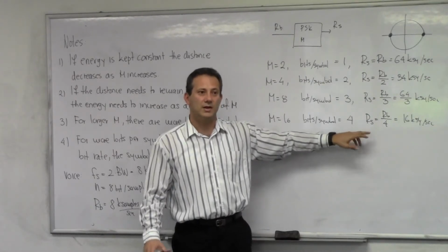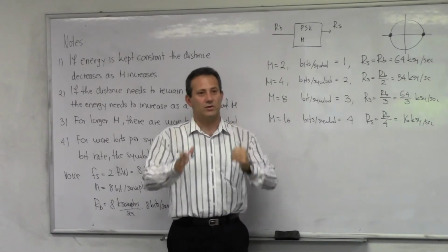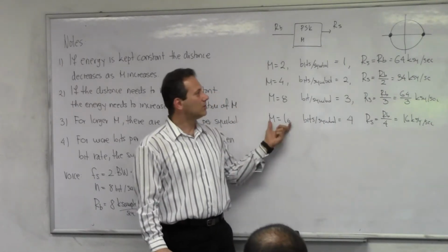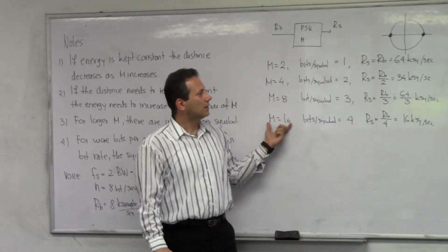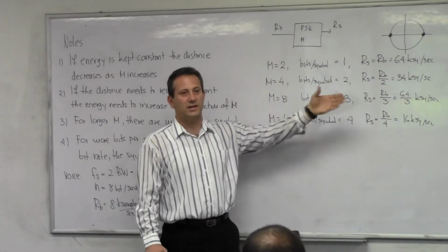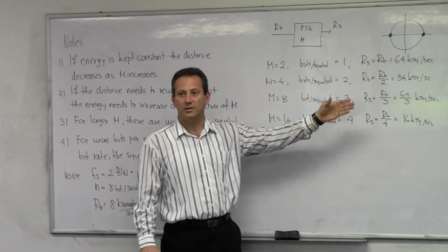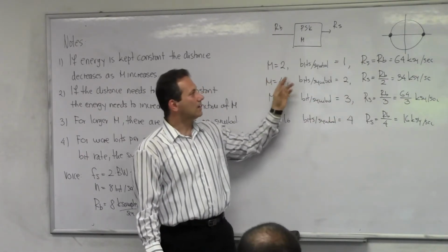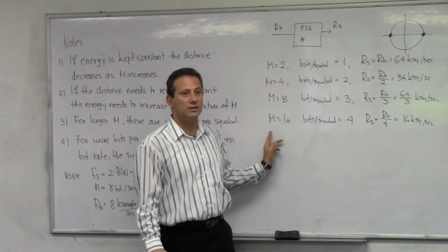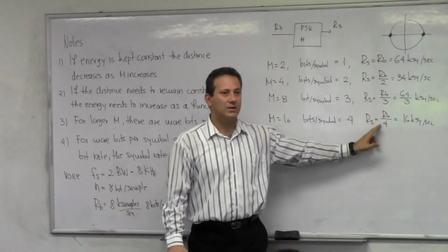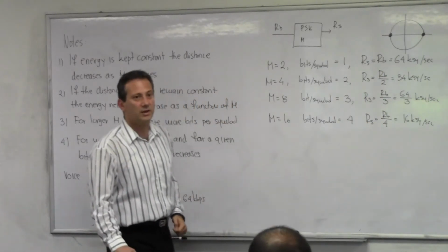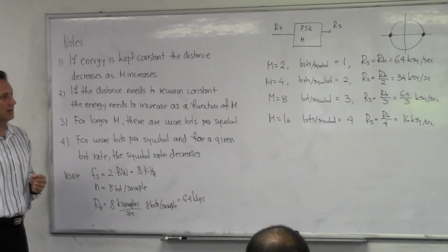So the lower this rate is, the narrower your signal is in the frequency domain. Right? So here we don't really have a fix. In AM we just translated our baseband signal to the carrier frequency, and we have 2W. Here, depending on how you modulate, your bandwidth at the carrier frequency may actually vary, and that's one of the important trade-offs that digital communication allows.